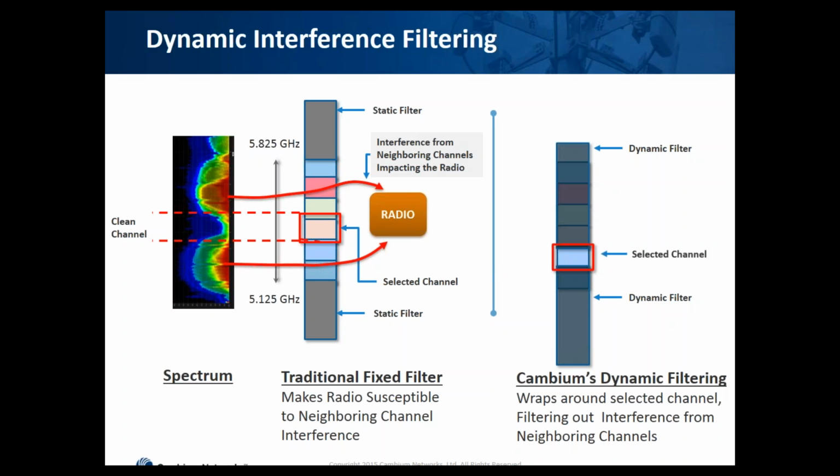Now, Sigar, how long have we had this dynamic interference filtering available? This has been some time. I think more than 12 months. This feature has been introduced, and it actually helps out, especially in really bad conditions where you have really high interference levels, especially on a really crowded tower where you have a lot of interference from different adjacent frequencies, especially with high power. This is really useful to filter out those unwanted adjacent channel interference. Great, thank you.